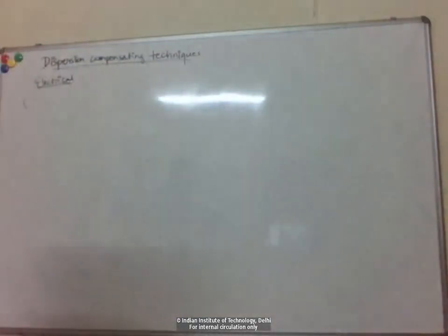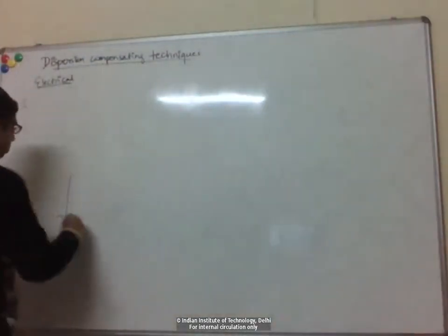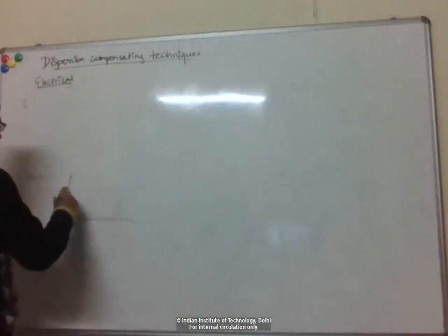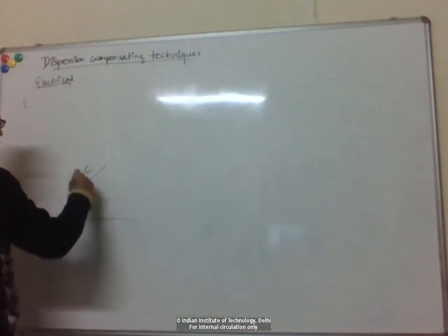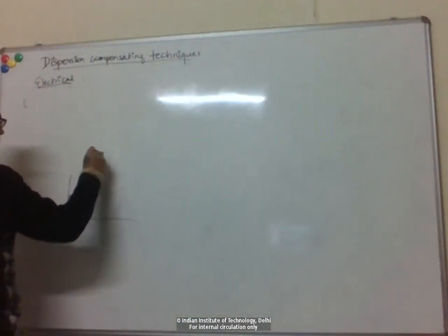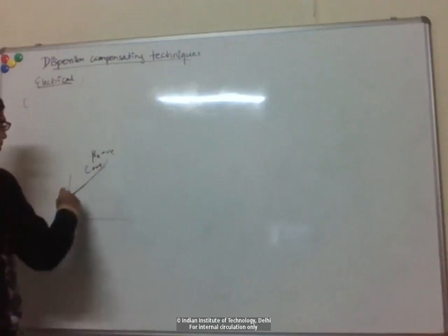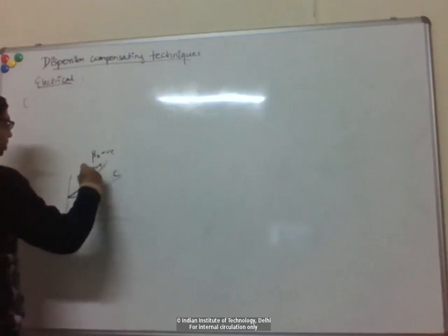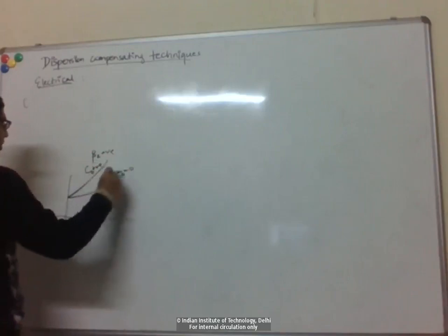So we saw the broadening if C is the same sign as beta 2. So let's say beta 2 is positive. If C was also positive, then the broadening was worst. If the input chirp was 0, then it was like this.